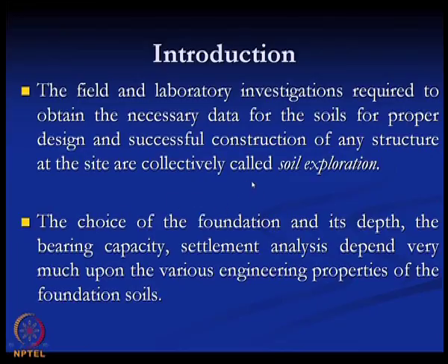The choice of foundation and its depth, the bearing capacity, and settlement analysis depend very much upon various engineering properties of the foundation soils. So, we should know the various engineering properties of the foundation soil before we start the design of the foundation. As I mentioned, the strength properties, that means c and phi, are very important properties for foundation design. Similarly, for the settlement calculation, the consolidation properties of the soil are also very important properties that we should know for the foundation design.